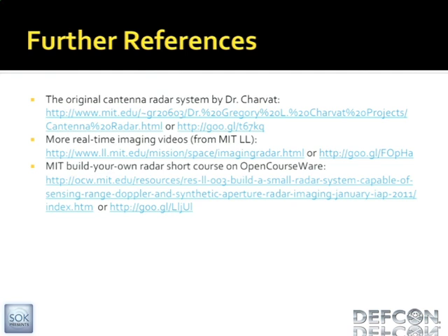Okay, yeah. To some extent, for the SAR stuff, we actually want something a little less directional than that. Part of it is that the coffee cans were what was available at the time. So MIT students drink more coffee. Well, that's probably true. Yes, we could graph that. But it's pretty open. You basically get different characteristics. If you're trying to do the SAR imaging, having a wide beam width is somewhat useful. It decreases some of your spatial fidelity, but you also get a wider image. If you have a very narrow beam, you're not going to get any signal from something that's further apart. So it's a trade-off there.